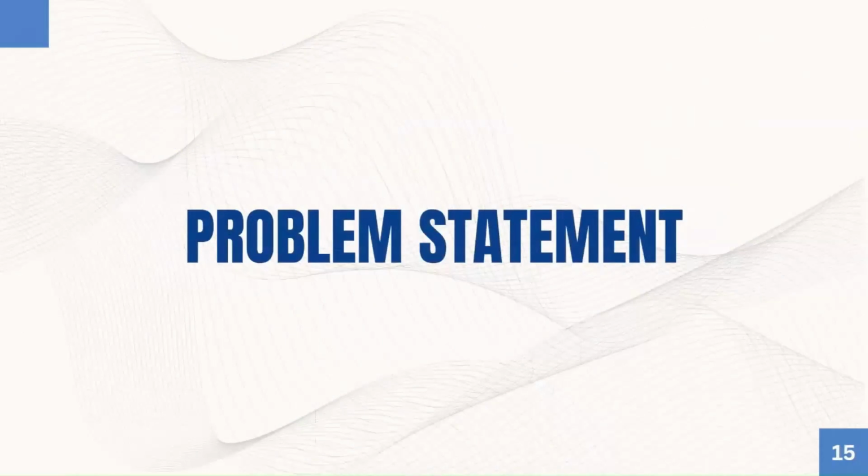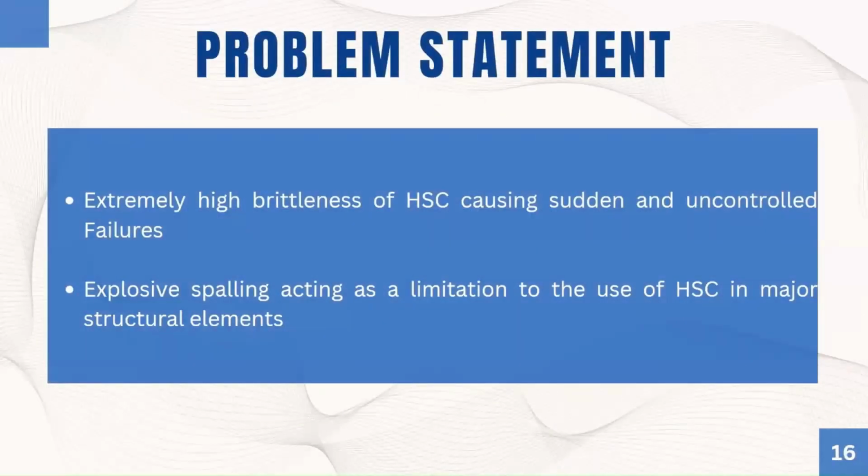Now, that brings us to our problem statement. The problem statement is as follows. First of all, was the extremely high brittleness of high strength concrete, causing sudden and uncontrolled failures. This was fixed using the steel fibers that we have introduced to the mix design.